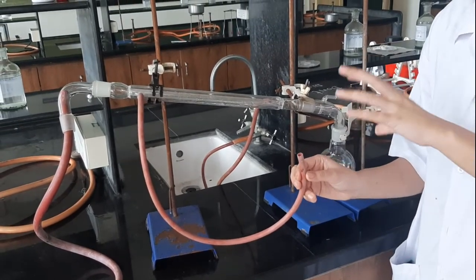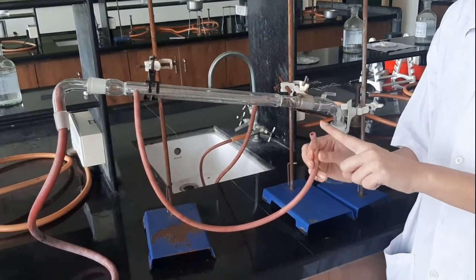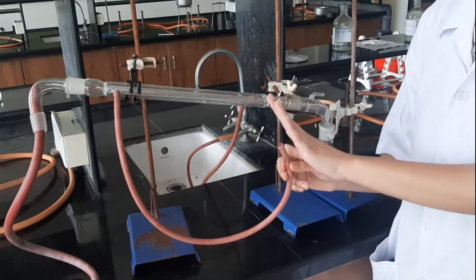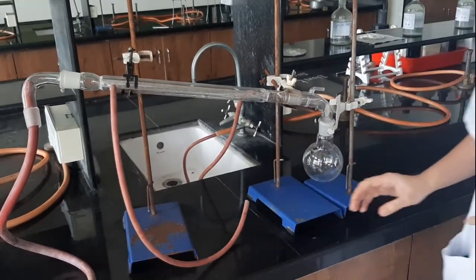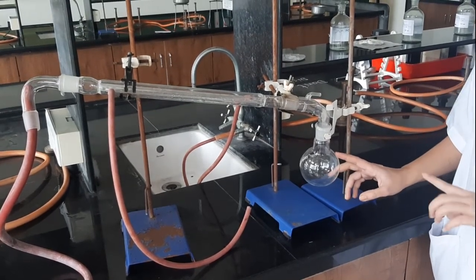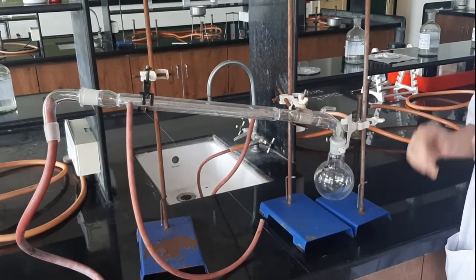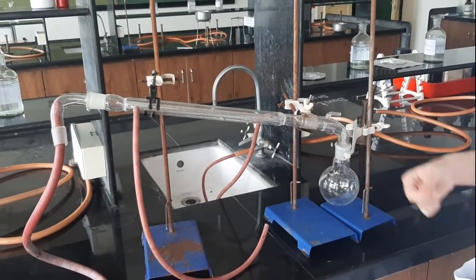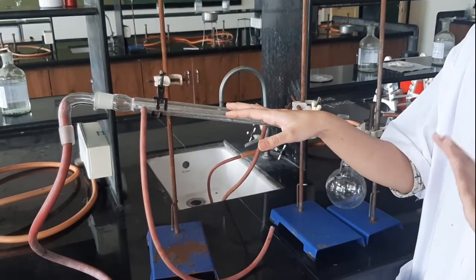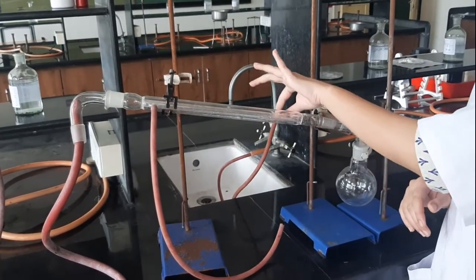Once those 5 minutes are over, we will measure the temperature of the water which is collected in the drum, and also we will measure its volume. Also we are going to measure the temperature of our distillate and its volume. That will be required for our calculation. The second thing we are going to do after that is arrange the setup for parallel flow. Then the water flow will be from here to the condenser and the outlet will be here.